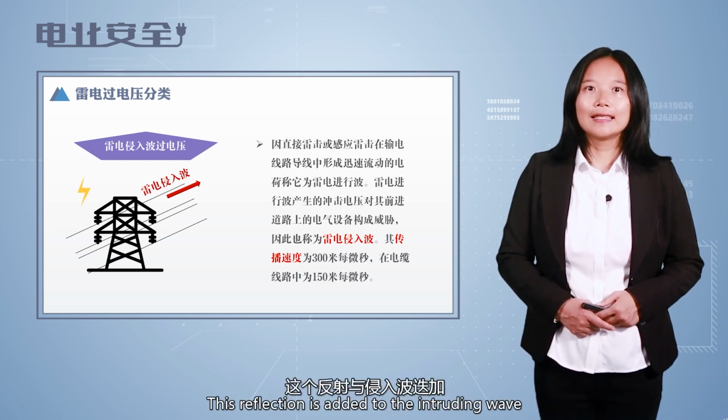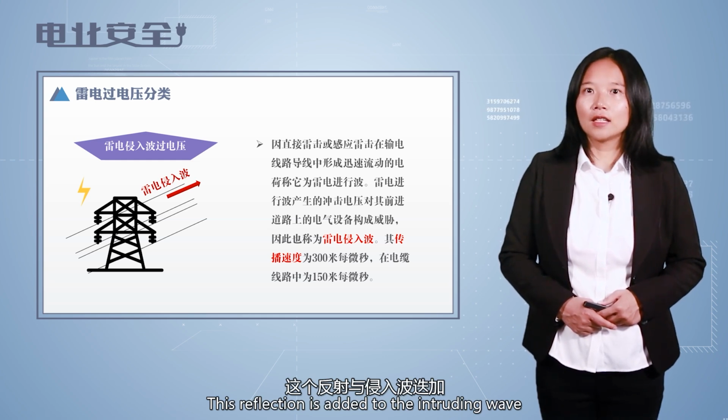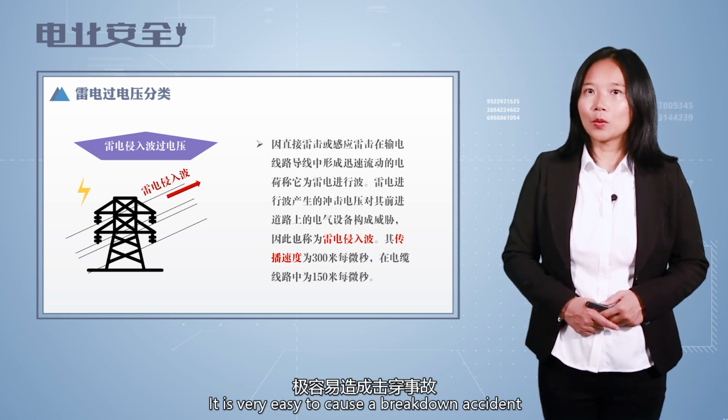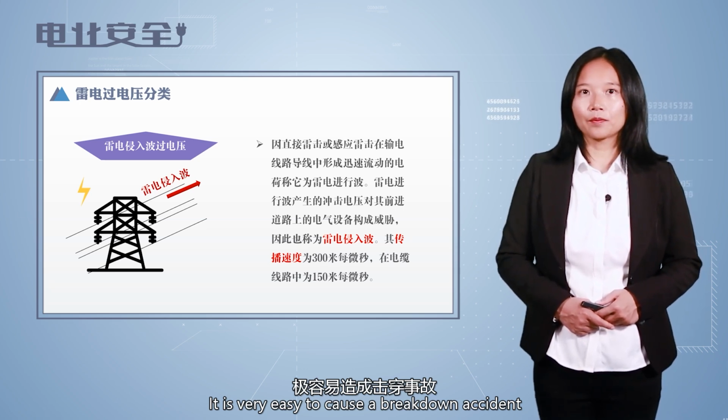This reflection is added to the intruding wave and doubles the overvoltage. It is very easy to cause a breakdown accident.